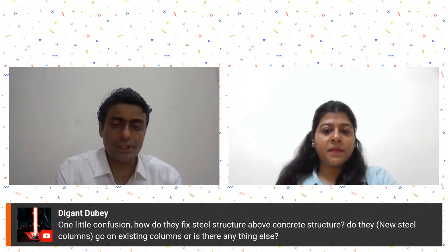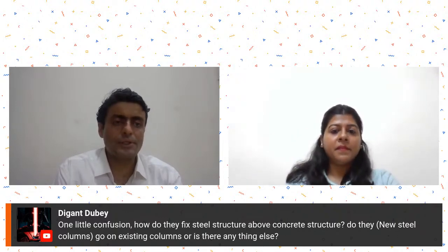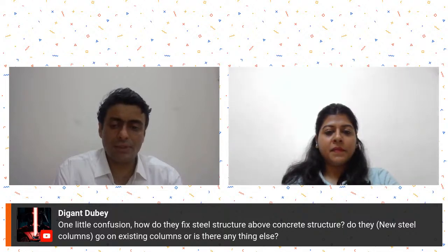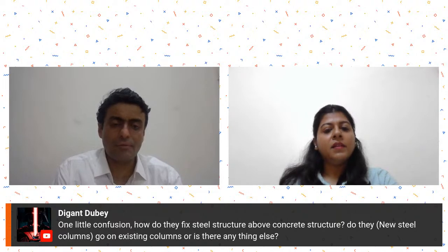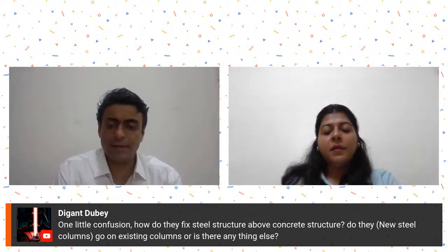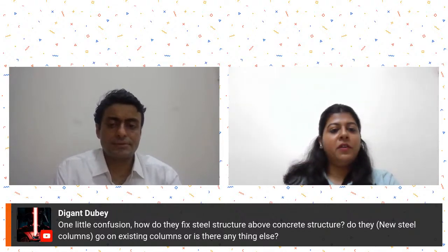But in the solar structures that your earlier company was doing, in these utility scale power plants that they set up, they generally embed the entire steel column inside the RCC pedestal. So that saves their time over there, because as you said, time is of large importance. So to save the time, they do it that way. Okay. Yeah. But for the data center here, we did a proper connection based design for that.